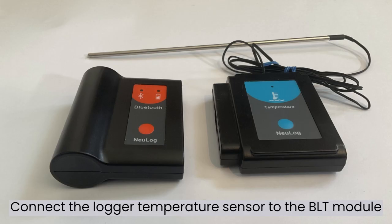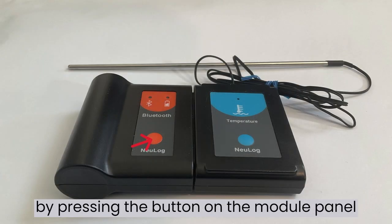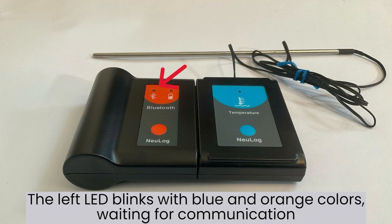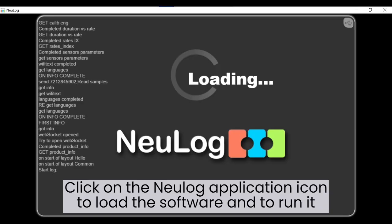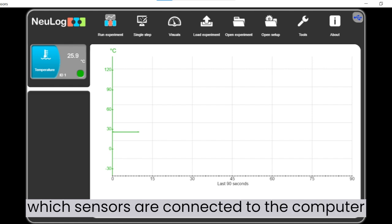Connect the logger temperature sensor to the BLT module. Turn on the BLT module by pressing the button on the module panel. The left LED blinks with blue and orange colors, waiting for communication. Click on NeuLog application icon to load the software and to run it. The software automatically identifies which sensors are connected to the computer.